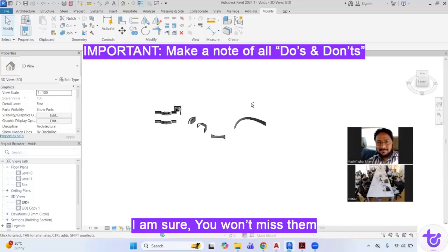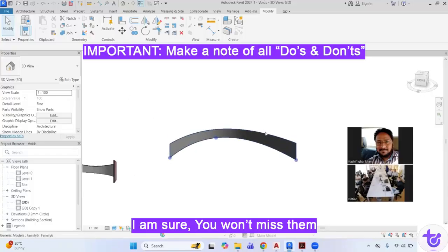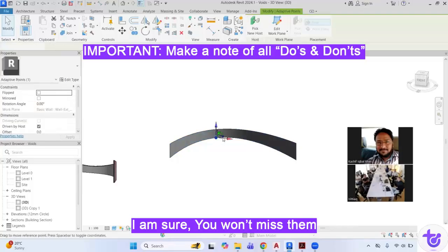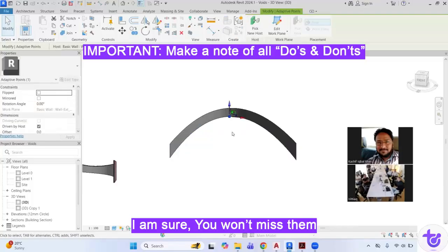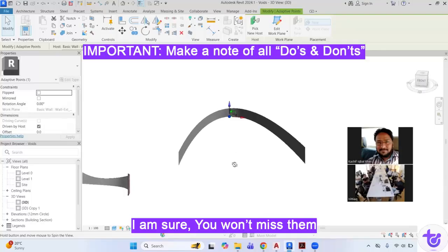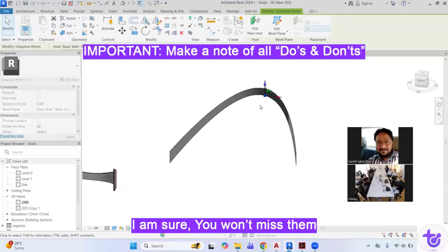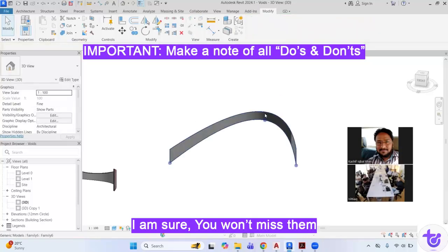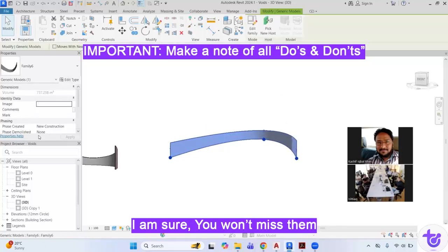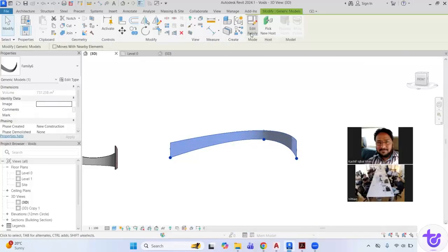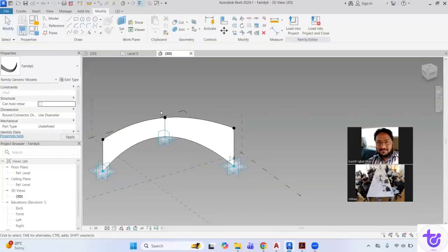You see, this has been placed. And now you can just select and press the Tab key to adjust the X, Y, or Z positions. Also, you can change the height from the parameters. Okay, I have just put the values directly. I did not create the parameter for the heights.